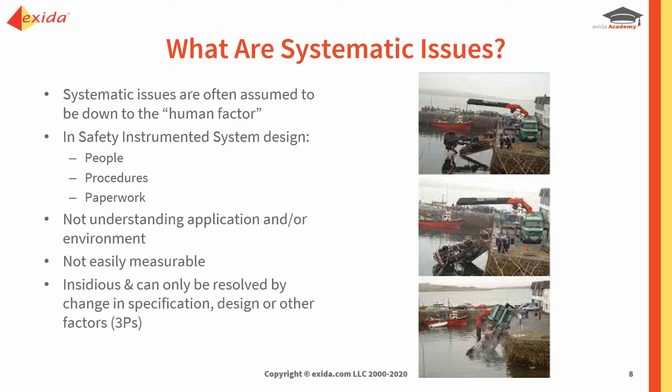There have been numerous instances where accidents have occurred because either the startup procedures were violated or weren't being followed, or there were shortcuts taken during maintenance, again not adhering to the procedures. And then the 3rd P is the paperwork, having the paper trail, making sure that we can prove we're doing what we said we were going to do. So this would be doing audits and making sure that proof testing is being done properly, mechanical integrity is being done properly, the procedures are being followed, etc.